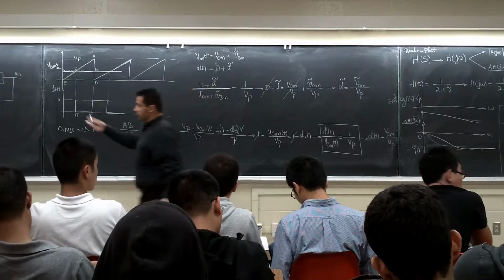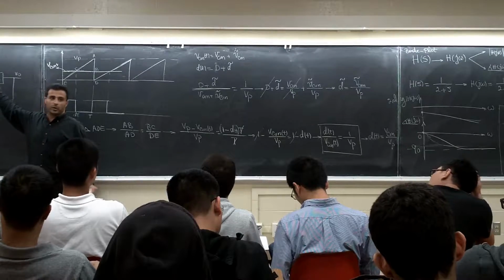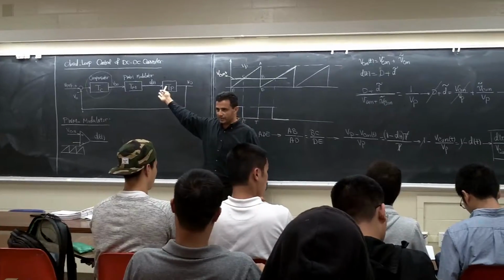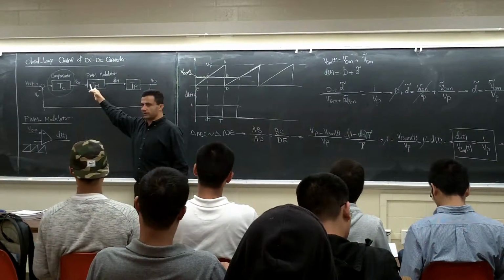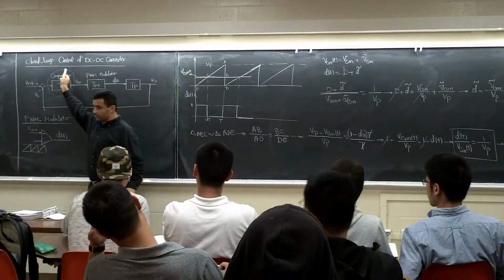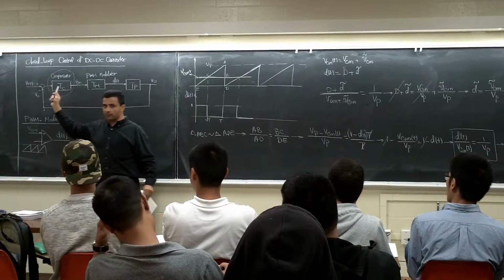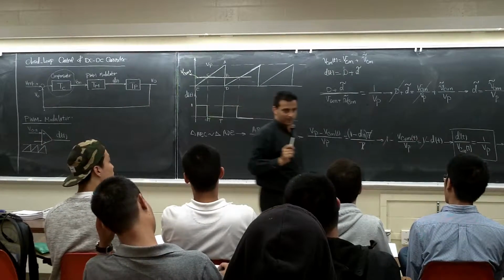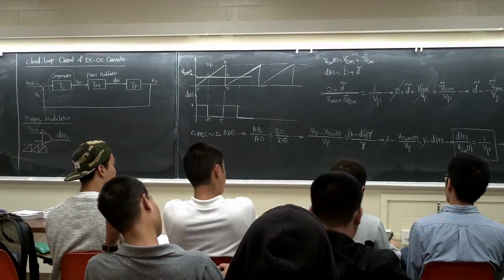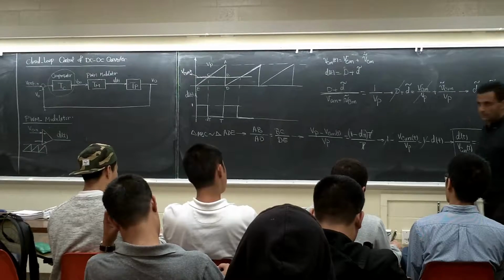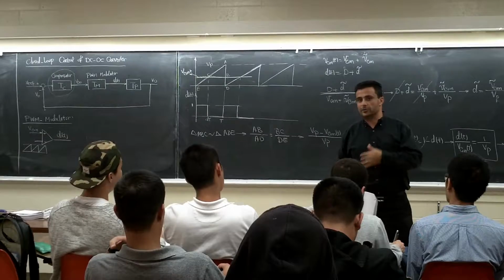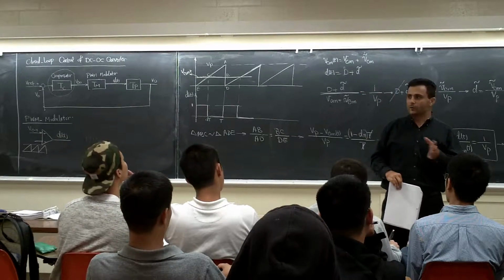If we have this, we can design the system. See, this one is not under my control, because this is whatever RLC you saw, the equation. Whatever is in the box is going to be there. I cannot change this one. This one is simple, this is 1 over VP, whatever is the peak of this one. I cannot change this one. But here is under my control. I want to design this system to have a phase margin of something between 45 to 60 degrees. So now my system is going to be pretty stable. Those who know a little bit more about control can go look at this. When we calculate this thing, you can plot the root locus of the system to see where we are.